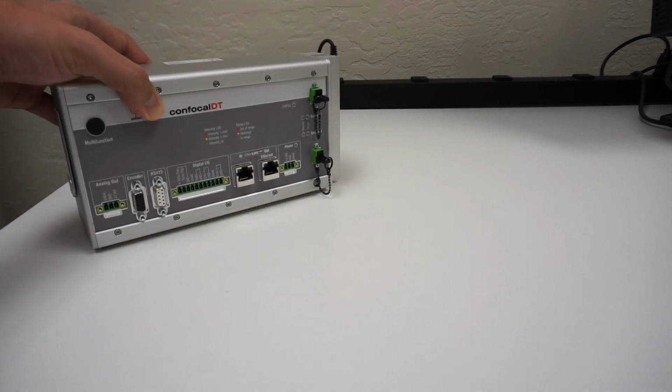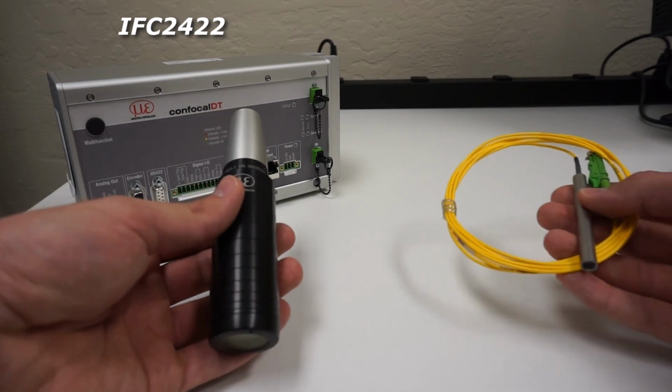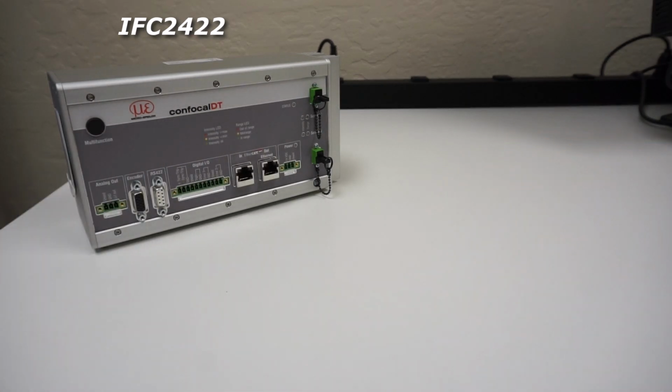As we discussed before, we first of all need a controller. Here we have a Micro-Epsilon IFC2422 dual channel controller, which allows for the simultaneous use of two sensors. And by the way, even if we would be talking about a single channel controller, multiple different sensors with different measuring ranges and shapes can be calibrated to such a controller. They can just not be used simultaneously then.